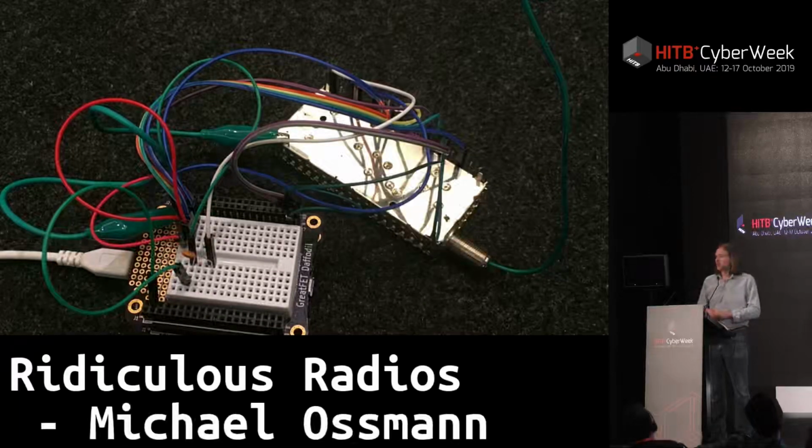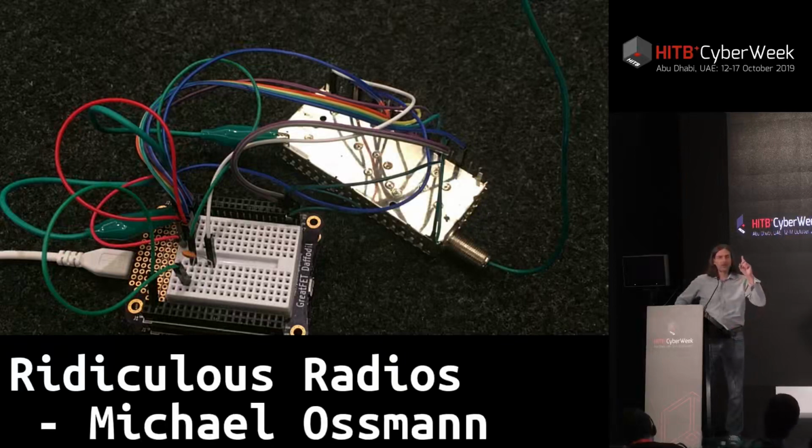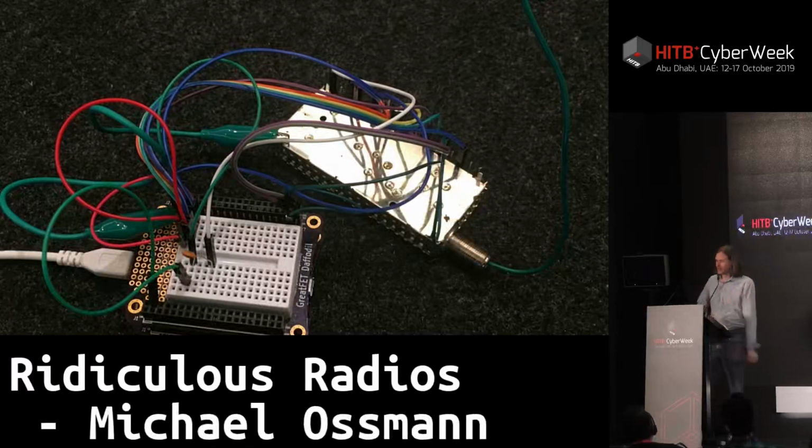It's a very simple radio receiver that is just the analog part. It's just the analog circuitry required to take a radio signal and pull the television signal out of it, but it doesn't actually interpret that television signal. It just shifts it, cleans it up, amplifies it, and shifts it down into a lower frequency range that could then be sampled by something like an analog to digital converter. So we still need the analog to digital converter here, but in this case we're using just one GPIO pin, a general purpose IO pin. We're just using a digital input as an analog to digital converter instead of using a proper analog to digital converter.